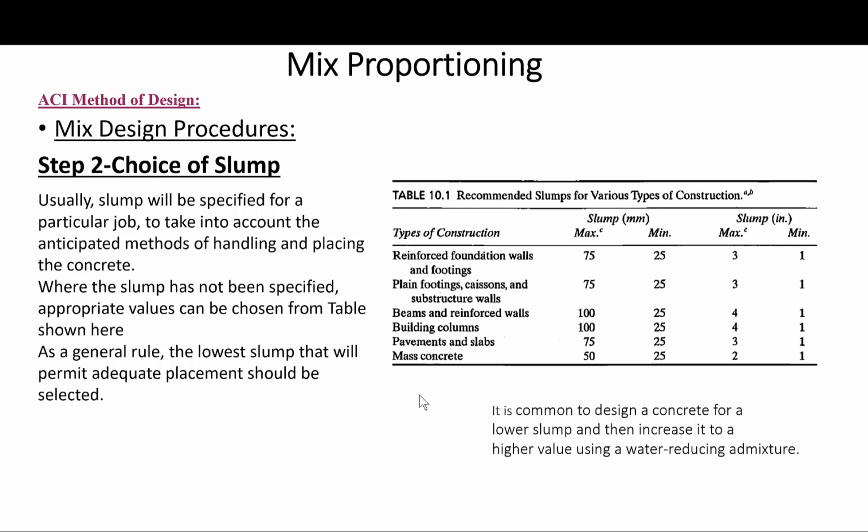Keep that in mind. It is becoming increasingly common to design concrete for a lower slump and then increase it to a higher value using water reducing admixtures. So that's probably the common practice nowadays. So workability issues can be overcome.